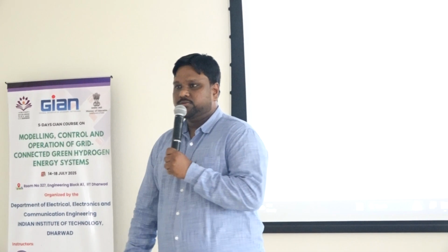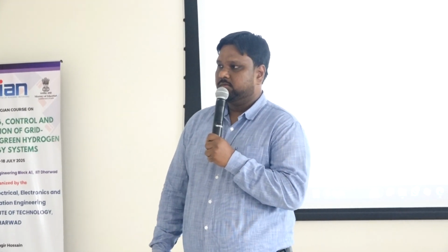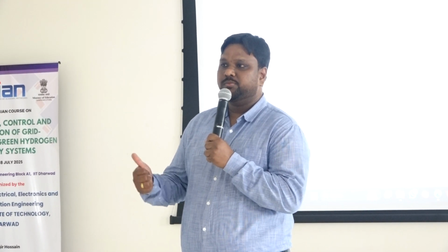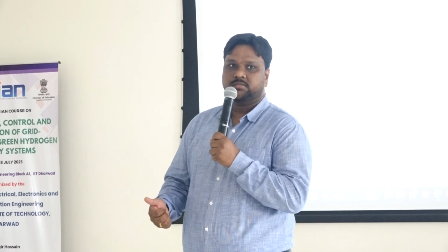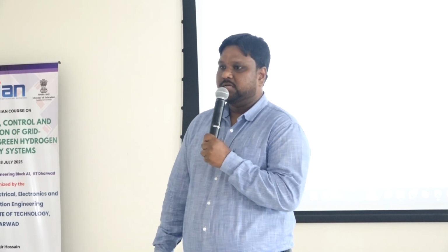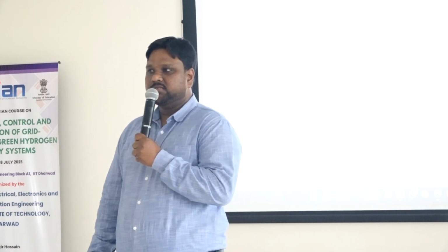Whether it is open loop or closed loop, you have to have some kind of pulse generation scheme. For DAB, yesterday, if you remember, I told you mostly three types are considered: single phase shift, double phase shift, or triple phase shift, SPS, DPS, or TPS. The simplest one is SPS. What does that mean?